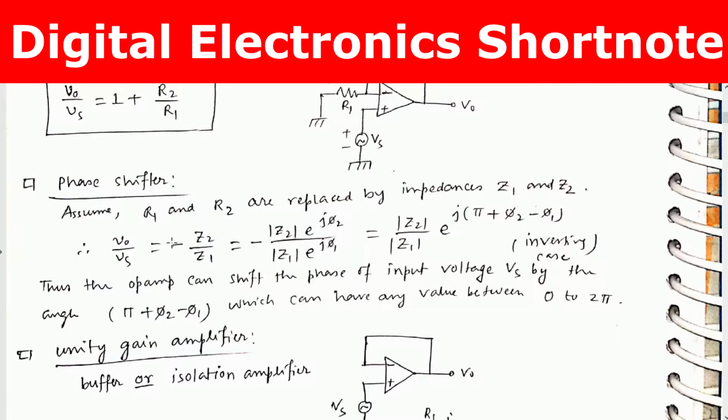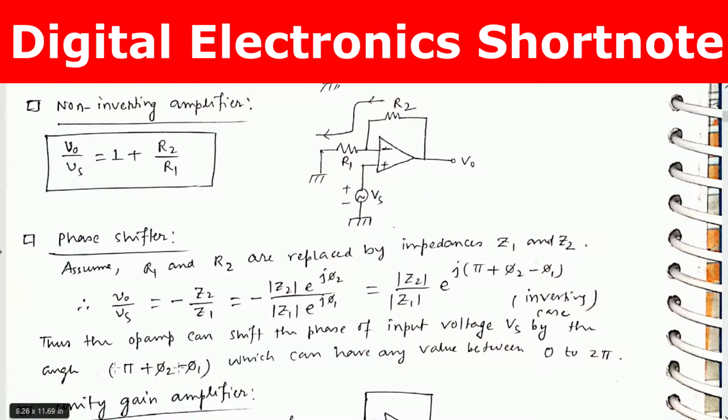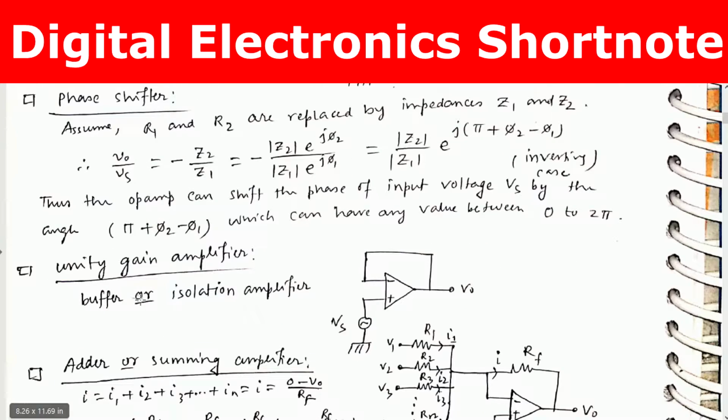Phase shifter: assume R1 and R2 are replaced by impedances Z1 and Z2. Then V0 by Vs equals minus Z2 by Z1, and considering phase we can write the modulus value of these things, and using the exponential function we can write the phase. Thus the op-amp can shift the phase of the input voltage Vs by the angle pi plus phi 2 minus phi 1, which can have any value between 0 to 2 pi.